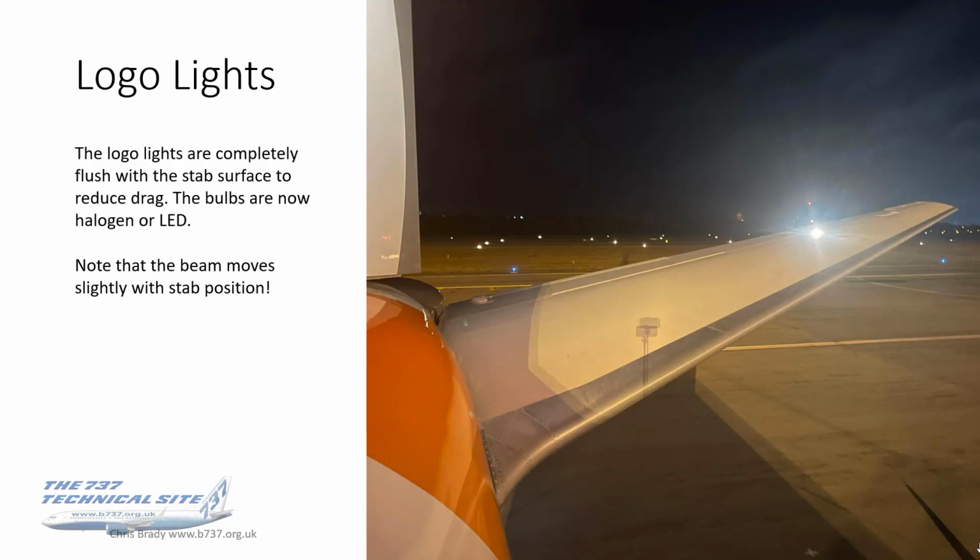The disadvantage, for what it's worth, is that the beam moves slightly with the stab position. As you've got a different stab trim, the stab will move, and the light will either shine centrally on the fin or slightly forward or slightly aft. But anyway, there you go.